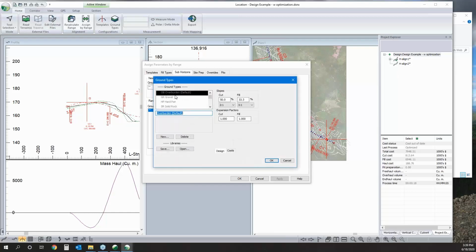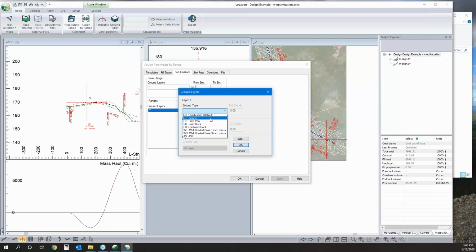So what these are is our material types, and I can say, let's go gravel, assume the material is gravel, over fractured rock, over solid rock. We can give it a depth of, let's go, 1.5 over 2.5. So this is 1.5 meters of gravel over an additional meter of fractured rock and then solid rock.